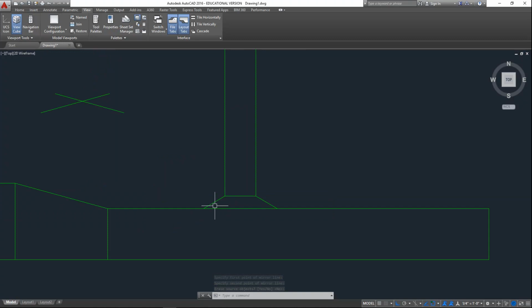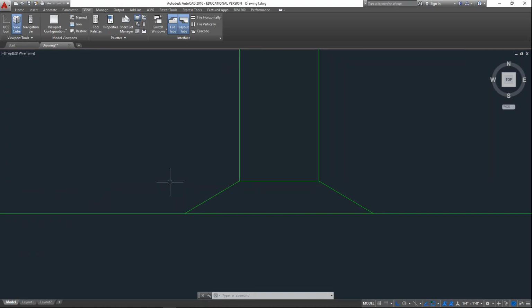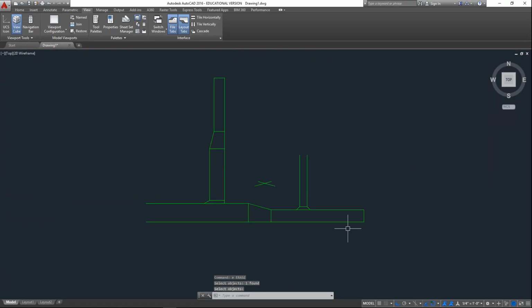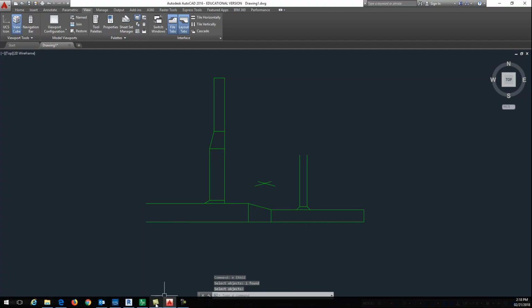And this is a pretty good size. A lot of times I like to use a 45 instead. So if I was going to use a 45, I would just draw my horizontal line and rotate 45. And you can see that if I use this, it's not taking up so much space on that duct. I can mirror this over. I can get rid of these. And that's my round duct takeoff.